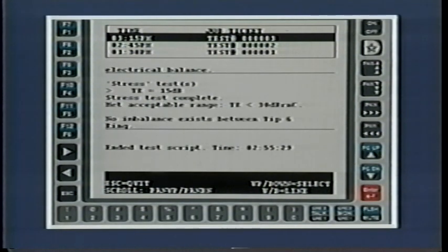If you're dispatched on a maintenance job, LDA can be used to test the circuit. Based on the results, you make the necessary repairs. Then use LDA to retest the circuit. The most recent test appears at the top of this list, and previous tests are further down the list. Page up and page down are used to highlight the desired test and the test results to appear.